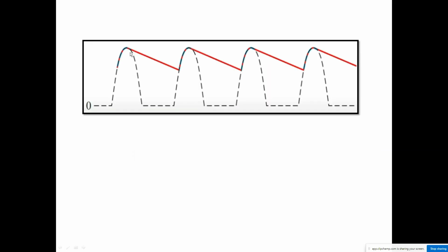The ripple voltage is nothing but the variation in the capacitor voltage due to the charging and discharging of the capacitor. As we know, the capacitor will charge up to the peak value and it will discharge until the input voltage exceeds the capacitor voltage. A smaller ripple voltage will provide the best filtering output. We can call it VR.